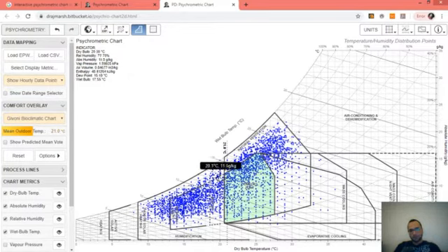If you proceed, then saturation occurs. For sure, here we are outside the comfort zone. And the minimum temperature that could be achieved by evaporative cooling is 18 degrees with 100% relative humidity. So you have around 11 degrees temperature drop from 29 to 18.